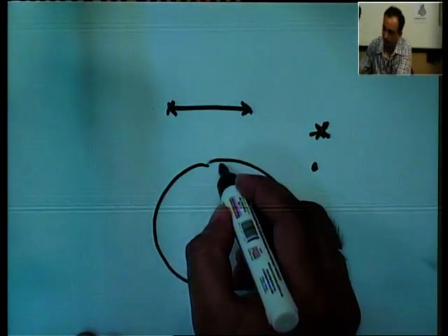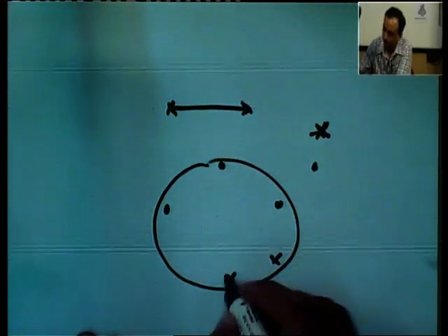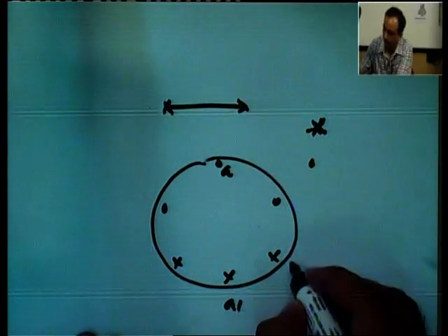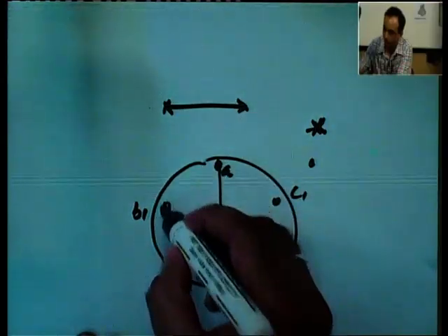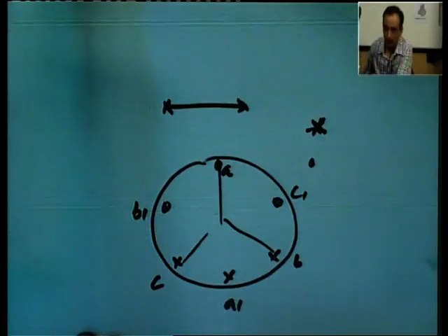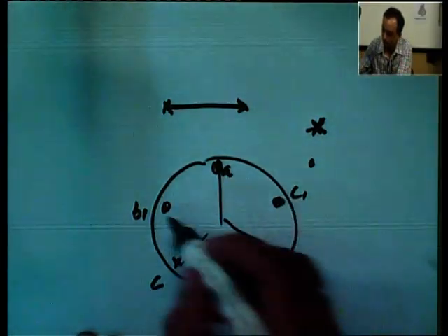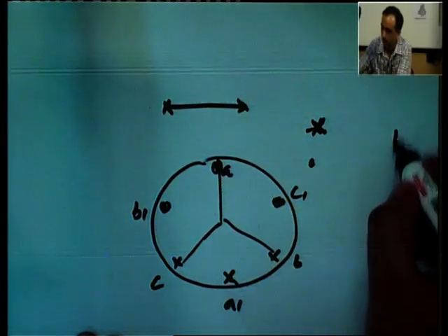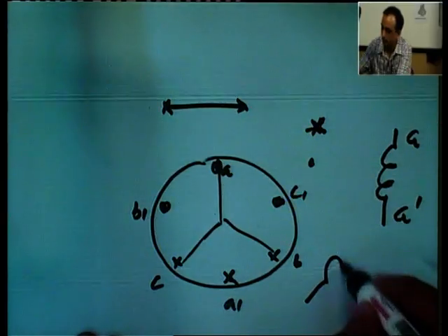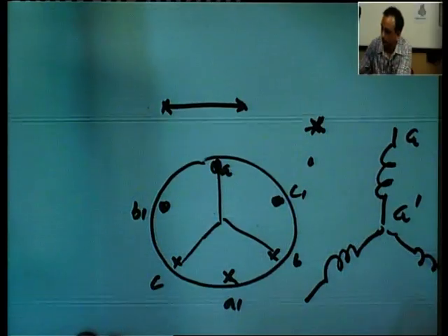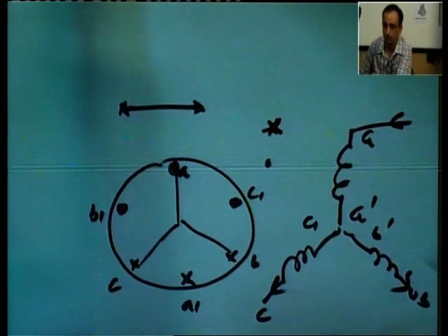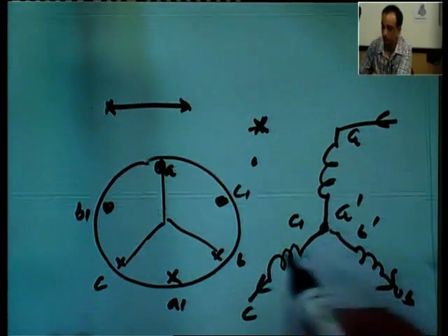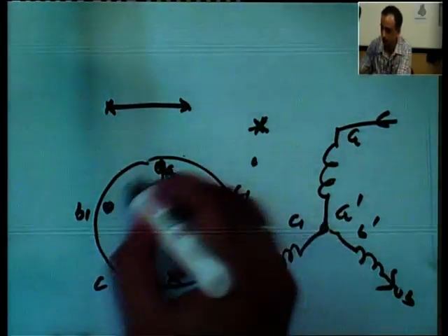That is the notation given in this case. In the rotor structure, we can take a particular instant where we have the structure like this: A and A dash, then B and B dash, C and C dash. They are 120 degrees apart from each other, and this notation can be easily obtained from the diagram that I showed you. What we have here is that current is entering from coil A and leaving from coil A dash. So, current can enter from this one and it is leaving from these two, B dash and C dash. It enters from here, and it leaves from these two.